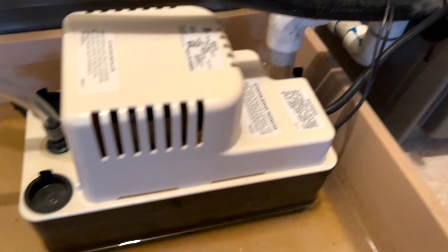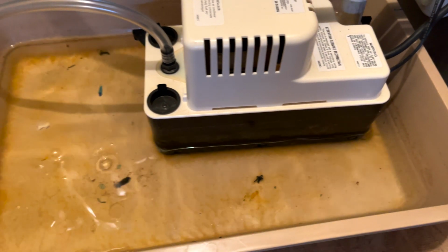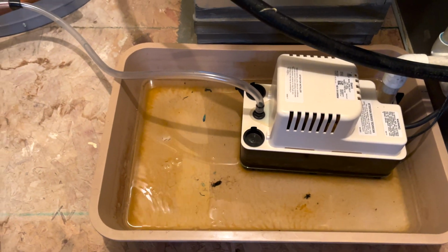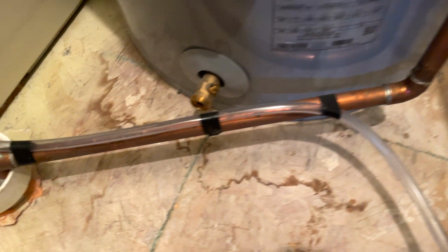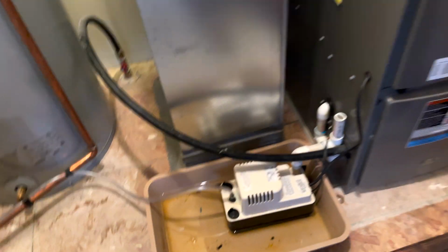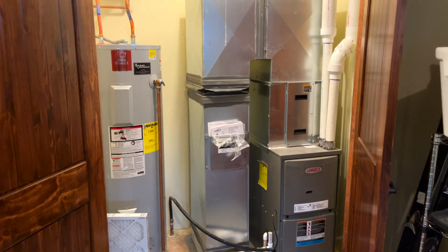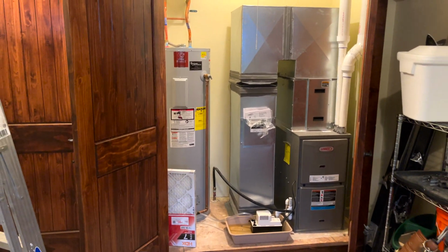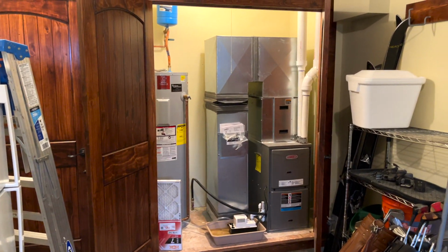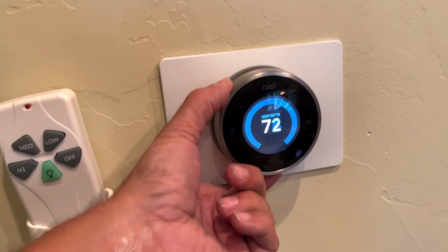And so there's condensate being created, and it's leaking into the pan. So good thing we got a bucket, because it's leaking. I don't know what's going on with the discharge. That looks like it's working, maybe it's not. So we've got a problem there. So we have condensate leak at the high efficiency gas furnace, right in the garage utility room, which also has a concern with the doors. Thermostat is in the living room, nice electronic one.